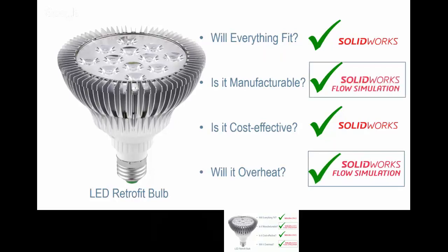SolidWorks Flow Simulation also can help us out with some of these other questions, like whether or not it's manufacturable, right? What if we're building a heat sink? It's going to help us understand if that heat sink is effective enough, how expensive it is going to be to manufacture that heat sink, or if it's cost effective. We might even be able to determine that a less expensive material could be used that functionally is exactly the same as a more expensive material like copper. Maybe you can substitute aluminum for copper.